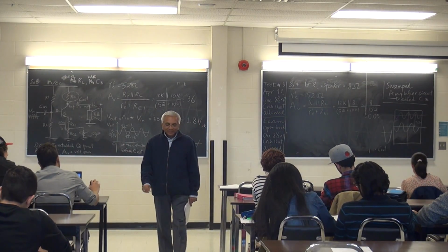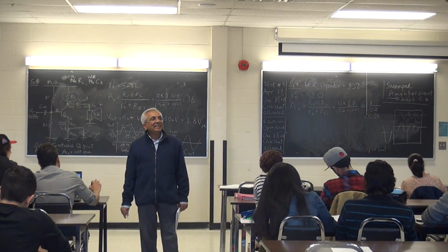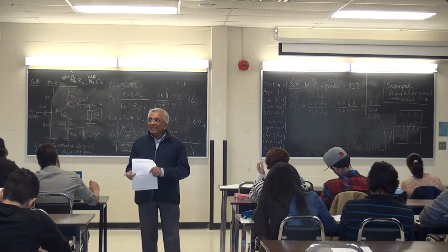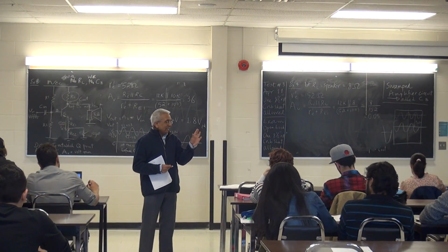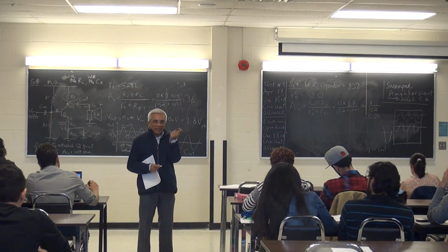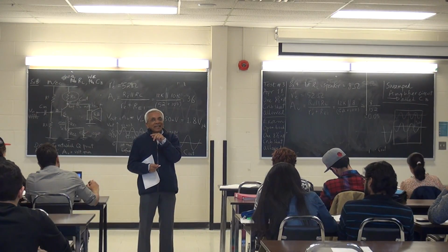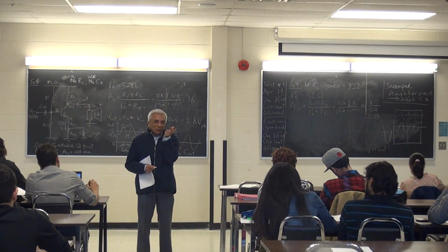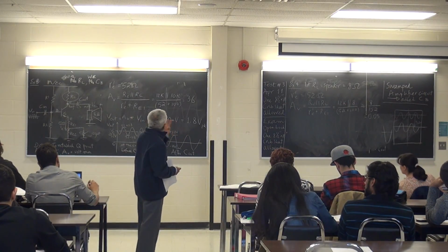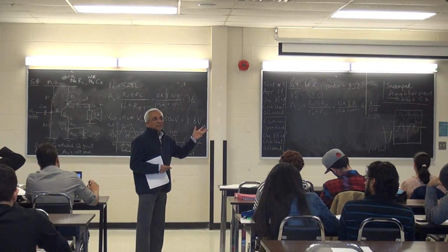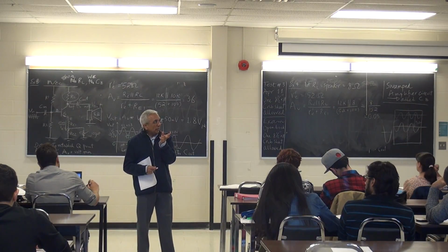So it says that now my gain, which I started out with a gain of 5, with no RL, no CV. Then I had a gain of 79 with CV. Then I had a gain of, what, 36 by having a 10K load.